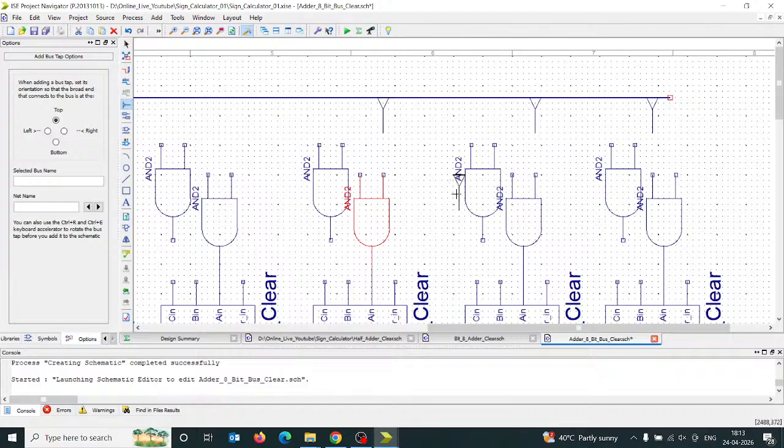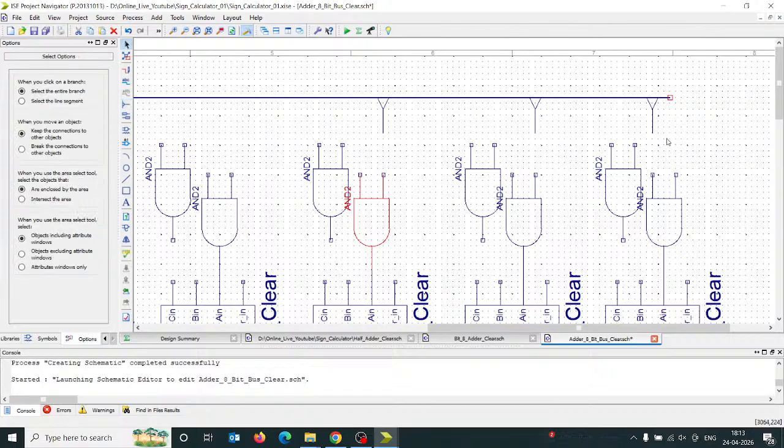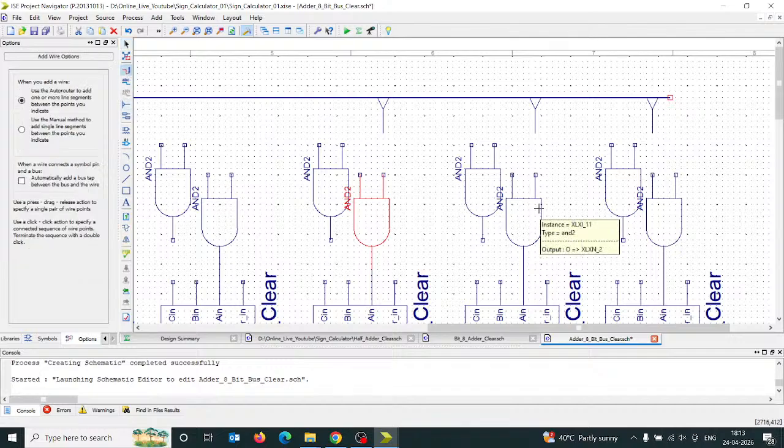So basically what I'm going to do here, I'm using the tab. The tab is connected to the bus wire, and with this bus wire, I'm going to connect my input A. How? A0, that is my A0, because it's 7:0. So the rightmost is my LSB and the leftmost is my MSB. Okay, like this.